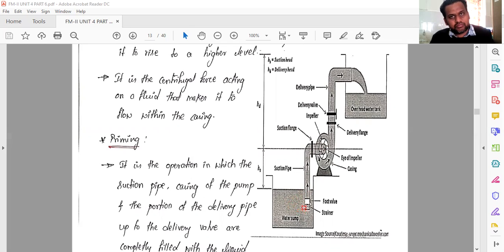ठीक है। सो जब तक ये पानी, जो भी पानी आपको पंपिंग करना है, तो उसको अगर ऑलरेडी आई ऑफ द इम्पेलर में कांटेक्ट है, तो इट विल बी इजी टू गेट सक। तो इसलिए आपको पहले बोल्ट या इधर एक वॉल्व रहता है, उसको ओपन करके इसके अंदर पानी फिल करते हो। जैसे पानी फिल करोगे इधर आके ये पूरा भर जाता है। देन जैसे मोटर ऑन करोगे ये तुरंत रोटेट होना स्टार्ट होता है, तो पानी ऑलरेडी है इसके अंदर, वो भी रोटेट होना स्टार्ट हो जाएगा।